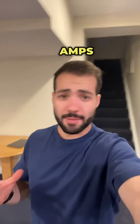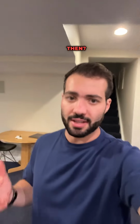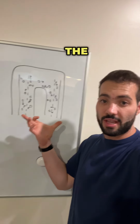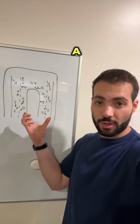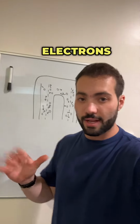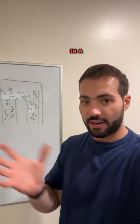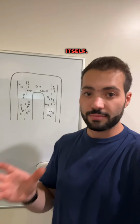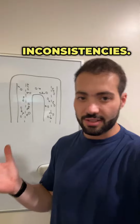So why do tube amps sound so different from solid state amps then? In a tube amp, the electrons come out of the cathode and will eventually reach the anode, being regulated into a cloud from the grid. Essentially, what this will do is take all the electrons and spread them around in a cloud, where it's only disrupted by the guitar signal itself. And this has some inconsistencies.